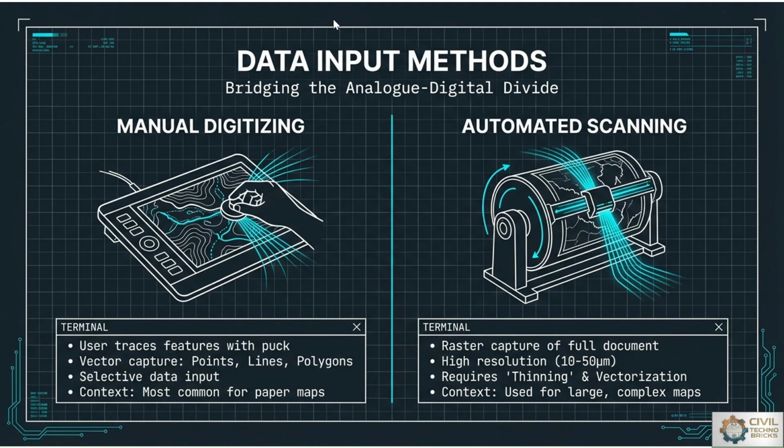For a civil engineer, this data comes from various sources like traditional survey or advanced total station surveys, GPS coordinates, scanned blueprints or satellite imagery. This stage is often the most time consuming part of a GIS project, sometimes accounting for up to 80% of the total effort. So quality control is paramount because spatial errors introduced during that input will propagate through all subsequent engineering analysis, leading to inaccurate quantity estimates or site layouts.